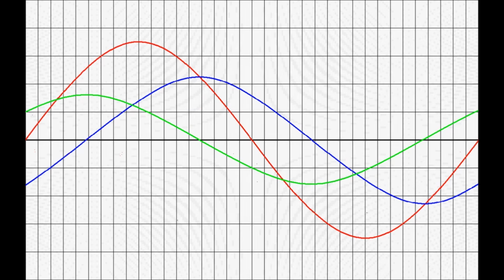Where does that put the current in relation to the source voltage? Let's figure that out. The capacitor voltage always peaks as it crosses the source voltage sometime after the source voltage peaks. The current always peaks 90 degrees before the capacitor voltage peaks. Therefore, the alignment of the current to the source voltage will be the lag angle of the capacitor voltage minus 90 degrees.